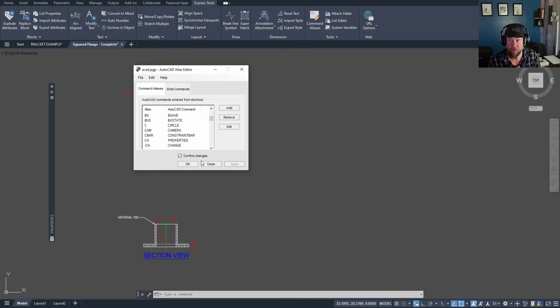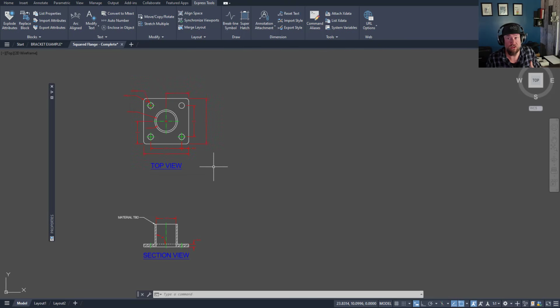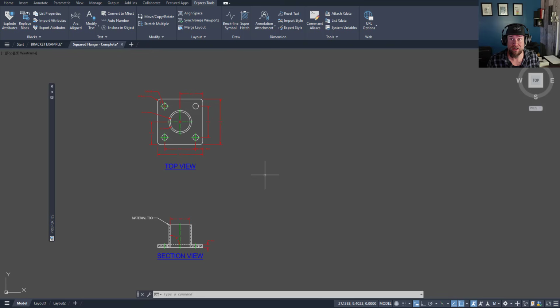This is a great way to save time within AutoCAD and is probably the quickest and simplest way to customize AutoCAD to work for you and not against you. If there are certain commands you're using a ton and find yourself wasting time searching for them, either in a hidden ribbon or panel, or typing them out fully, adding that alias or figuring out what the existing alias is a huge time saver.